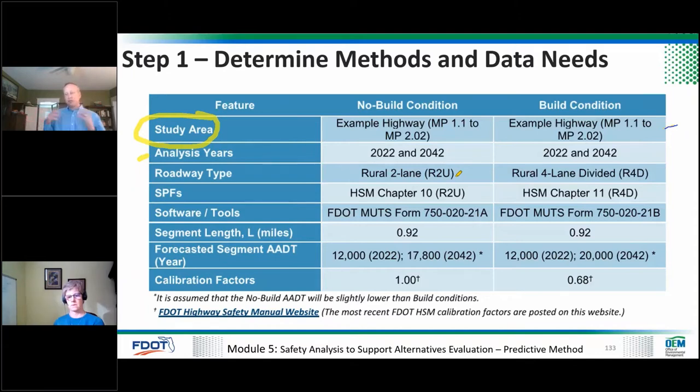And you can use linear interpolation. I would just say that with safety, that isn't necessarily an exact number if you linearly interpolate the crashes, because the safety performance functions are curves. So it's not a straight line between the two endpoints, but that is an approximation that could be used. When you use tools, like Beth mentioned, IHSDM, it will do all of the calculations and linearly interpolate the volumes, or you can put in volumes, and then you get a more exact set of numbers.